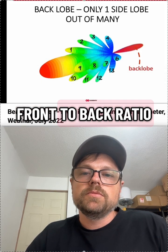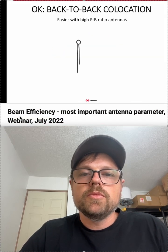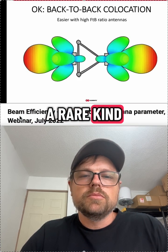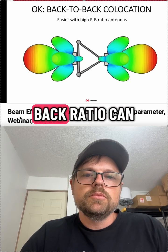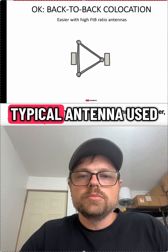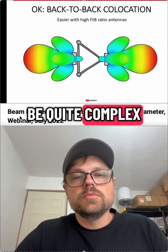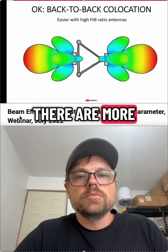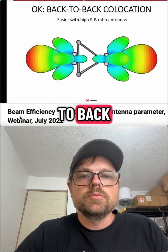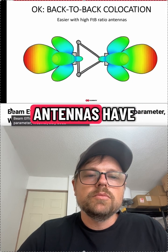Interpretation of front-to-back ratio: it doesn't say anything about all the other side lobes. When two antennas are exactly back-to-back, which, let's be honest, is quite a rare scenario, a high front-to-back ratio can help to decrease the interference level the radios see. But as I said before, a typical antenna used with these networks has a lot of side lobes, and the back lobe itself can be quite complex at the same time. As soon as there are more links on a tower, or collocated antennas are not exactly back to back, you are looking at noise issues coming your way because of all the other side lobes that these antennas have.